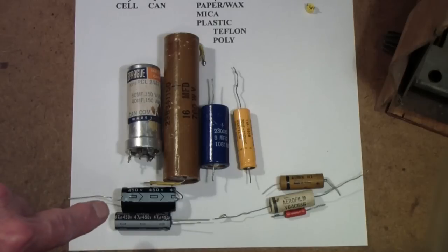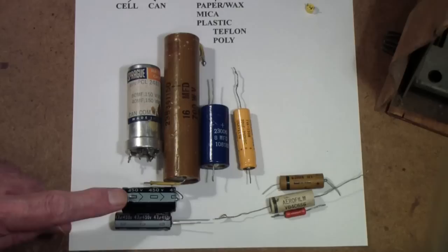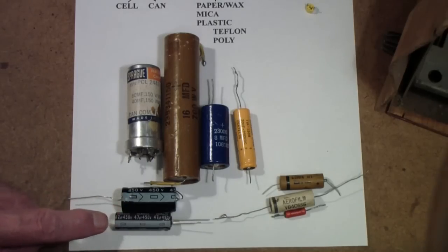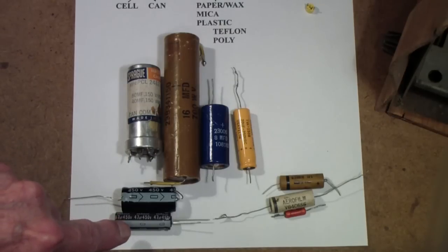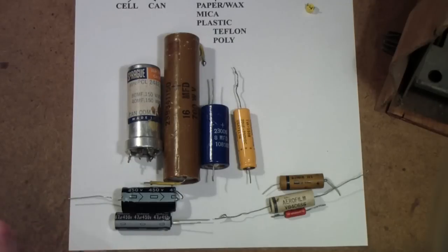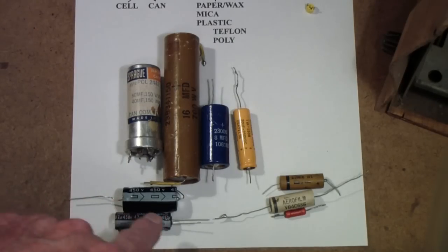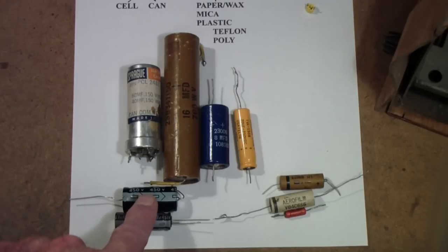These are a couple of modern capacitors. This is a 50 microfarad, 450 volt. This is a 47 microfarad, 450 volt. So you would think that this would be the better capacitor, but actually this one is. This one is rated up to 105 degrees centigrade, whereas this one is only rated to 85. And you may notice one other thing about these two. This one has the leads coming out of the ends. There's one over here that's bent back, and then one here. This one, on the other hand, has both leads on this side. These are called axial lead, and these are called radial lead.